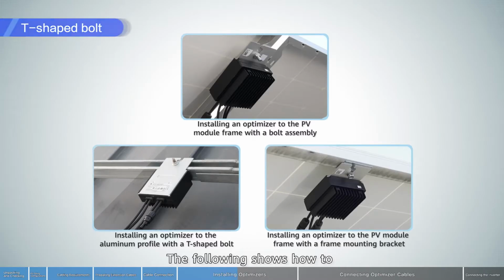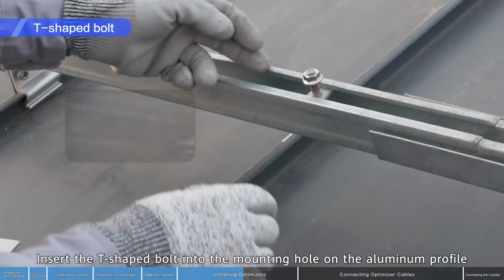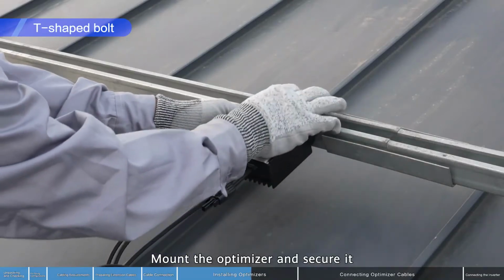The following shows how to install an optimizer to the aluminum profile with a T-shaped bolt. Insert the T-shaped bolt into the mounting hole on the aluminum profile. Mount the optimizer and secure it.